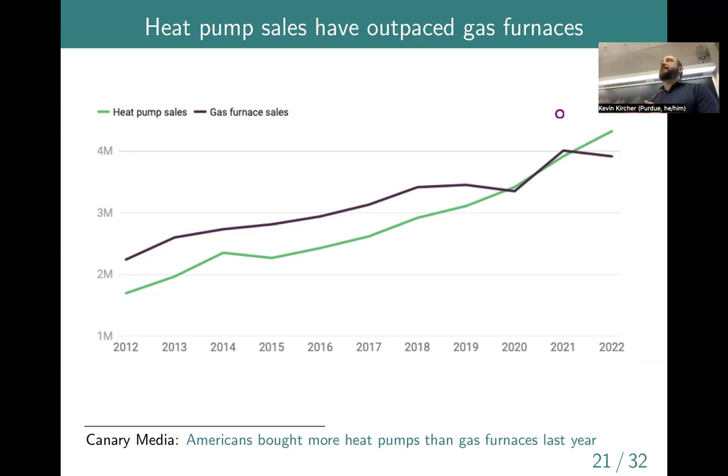So for certain things, absolutely yes. If you heat with electric resistance, it's basically always going to be better to use a heat pump. It's always more efficient. If you use heating oil or propane, these tend to be somewhat less efficient and higher cost fuels. So the cost per unit of heat output is typically significantly higher for those than for heat pumps. The real competition is between natural gas and electric heat pumps, and there it's really location dependent and price dependent.